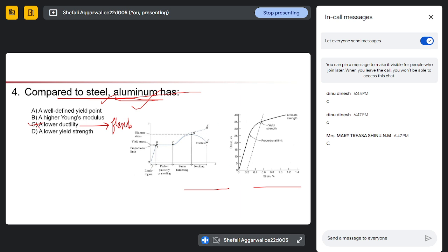If you see from these two graphs, normally in mild steel we have a yield stress of 250, right? And it can be 415 or 500, something like that. It depends on what the carbon content is, or what the different heating or cooling temperature is.